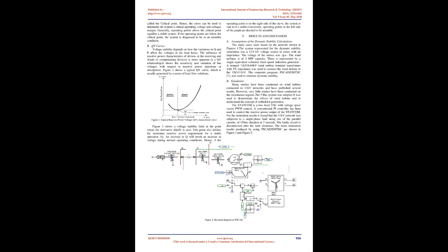follows. The Statcom belongs to a family of power electronics controllers that base their operation on the voltage source converter principle. The most basic configuration of the Statcom consists of a 2-level VSC with a DC energy storage device, a coupling transformer connected in shunt with the AC system, and associated control circuits. The DC energy storage device may be a battery, whose output voltage remains constant, or it may be a capacitor, whose terminal voltage can be raised or lowered by means of suitable converter control.